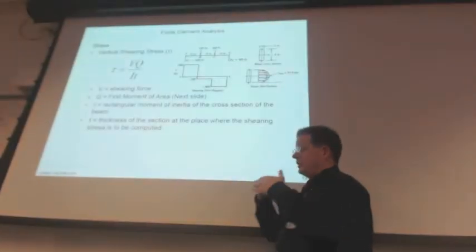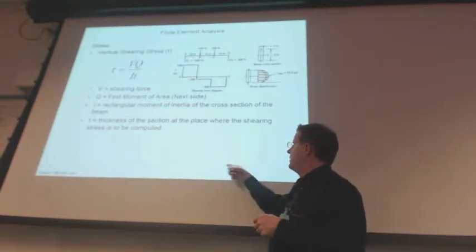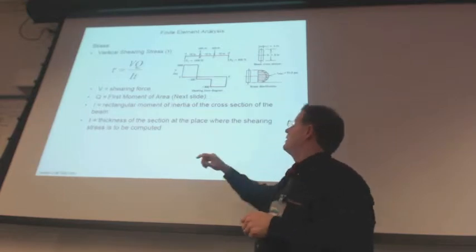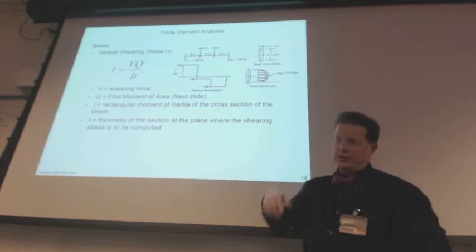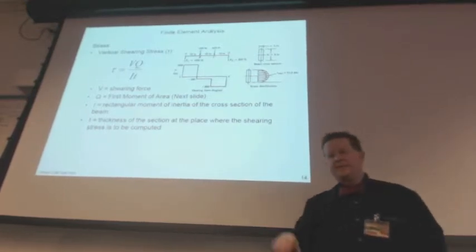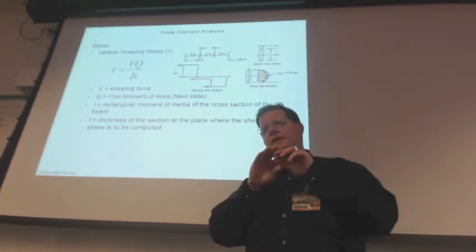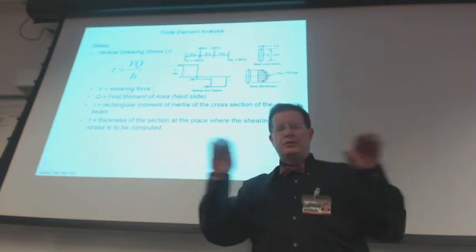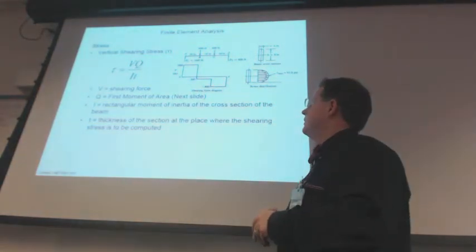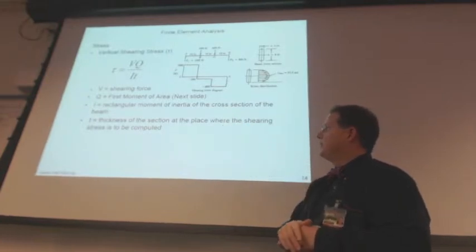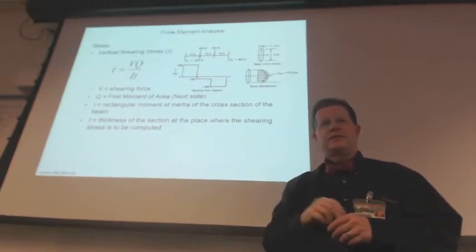Now if I created some shear horizontally on my element, it's got to be equal all the way around, so I'm going to have some shear vertically as well. But it will create a distributed shear load on the end with the neutral axis having the maximum shear because our Q, first moment area, is the largest at the neutral axis.